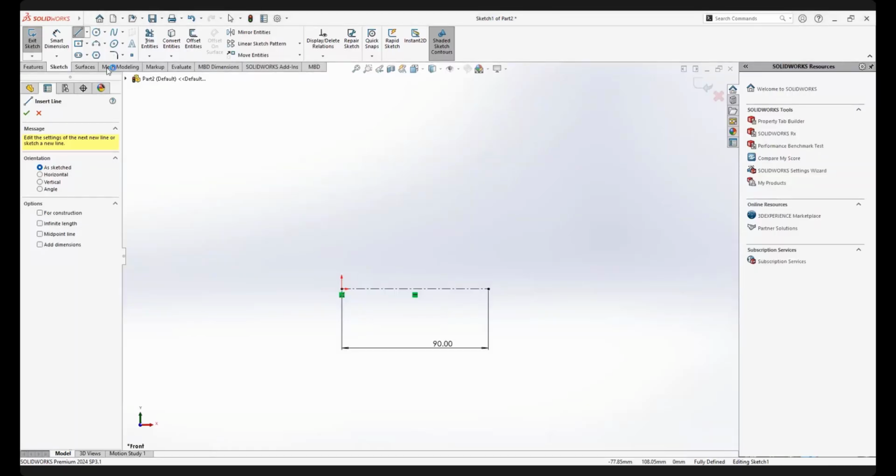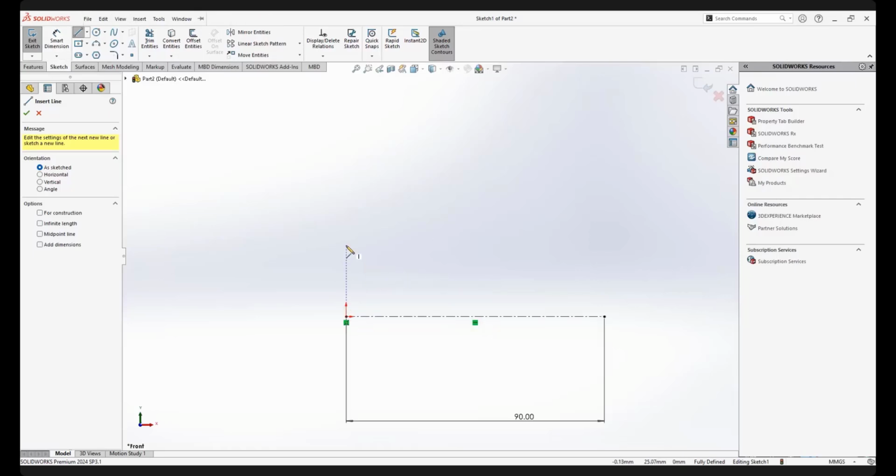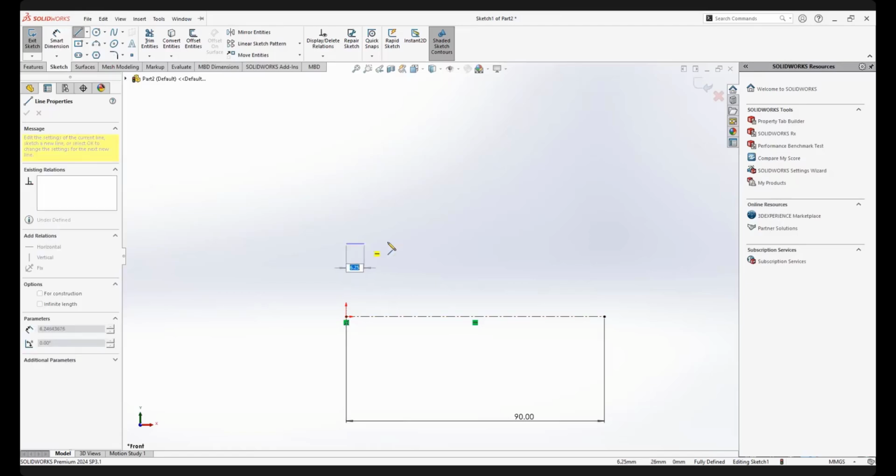So in Solidworks, I already drew the center line. I'm now in line, sketch mode. So I will start at this low. Can you see it's kind of like a tracking dot? It means it will be in line because this is my origin. Here. So I will draw simply the shape